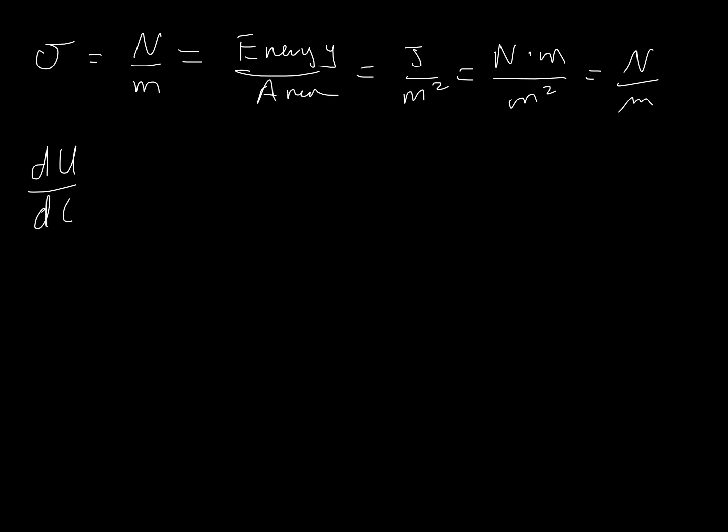We're going to redo a new energy balance, but we're going to include this surface energy term. So it should look very similar, except we've added one extra term on. This is a closed system transient energy balance. dU/dt is the total change in energy as a function of time. The only two ways that we can physically interact with this system from an energy perspective is giving it heat, which is Q, and physically expanding or contracting it, which is the PdV term here.